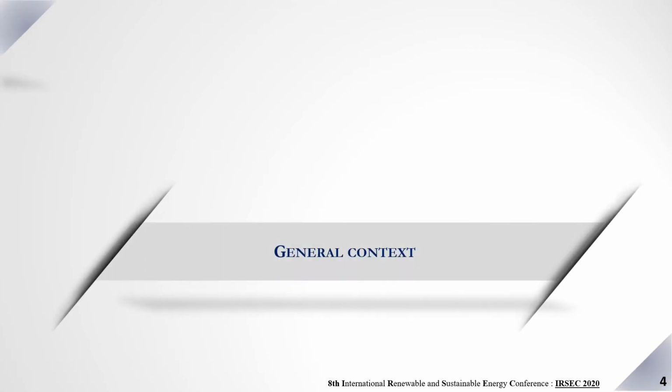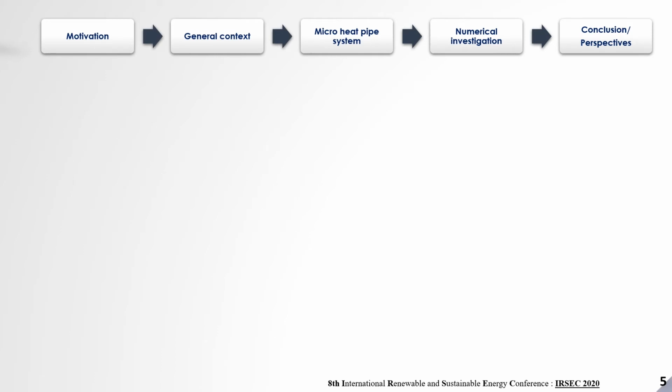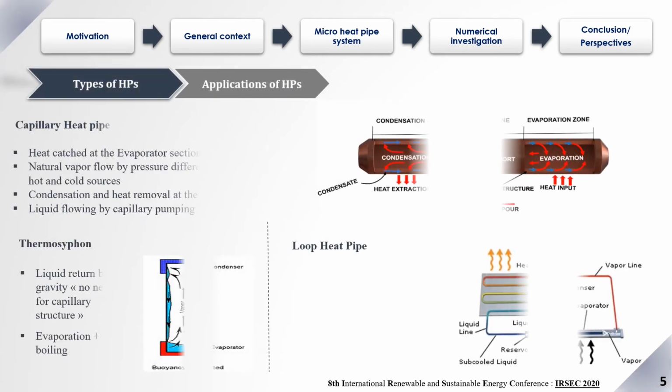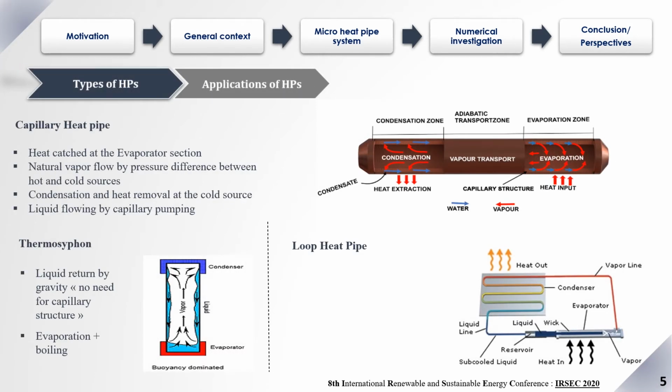There are a lot of families of heat pipes, but the working process is a little bit the same with some small exceptions. The first one is the capillary heat pipe, which is a heat transfer device that combines the principles of both thermal conductivity and phase transition to effectively transfer heat between two solid interfaces. The heat input vaporizes the liquid working fluid inside the wick structure in the evaporator section. Then this latent heat flows toward the condenser to release heat to the cold environment.